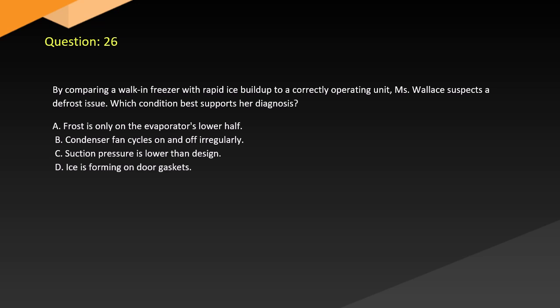Question 26. By comparing a walk-in freezer with rapid ice buildup to a correctly operating unit, Ms. Wallace suspects a defrost issue. Which condition best supports her diagnosis? A. Frost is only on the evaporator's lower half. B. Condenser fan cycles on and off irregularly. C. Suction pressure is lower than design. D. Ice is forming on door gaskets.